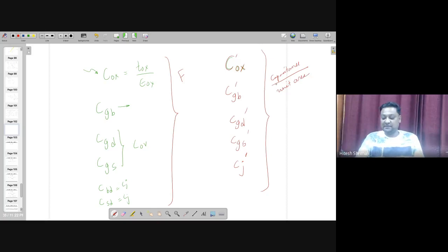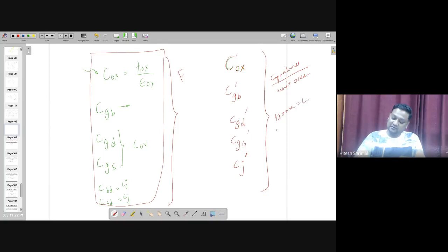So this capacitance is actually divided with respect to the unit area. So if the minimum area given for the technology is 120 nanometer length and 220 nanometer of width, then you have to divide by that unit area, right? So that's how they have to be calculated.